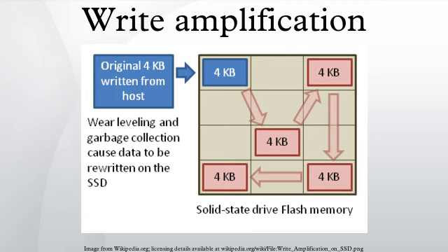Separating static and dynamic data. The separation of static and dynamic data to reduce write amplification is not a simple process for the SSD controller. The process requires the SSD controller to separate the LBAs with data which is constantly changing and requiring rewriting from the LBAs with data which rarely changes and does not require any rewrites.